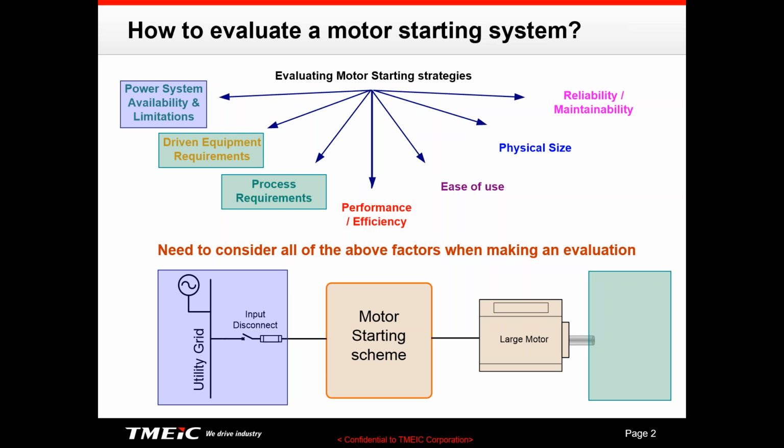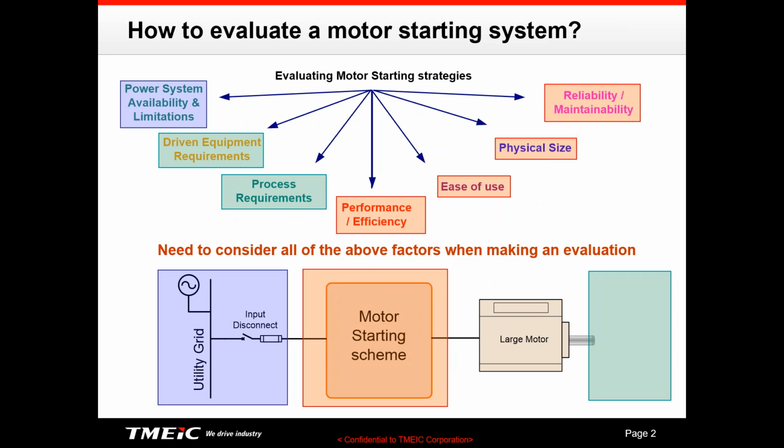Which starting method will provide the best performance and efficiency, and which will be easy for the operators to use? What is the physical size, especially if the site has very limited space, and how is it going to be maintained, and what are the reliabilities associated with my starting scheme? I need to consider all of these factors when I'm making an evaluation.